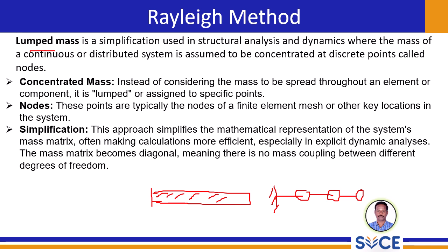When using Rayleigh's method with a lumped mass system, our assumed displacement vector x would contain the maximum displacement of each of these lumped masses. The stiffness matrix K would then represent the relationship between these displacements and restoring forces at those particular locations alone. We would use the Rayleigh quotient with the diagonal mass matrix and the appropriate stiffness matrix to estimate the natural frequency.